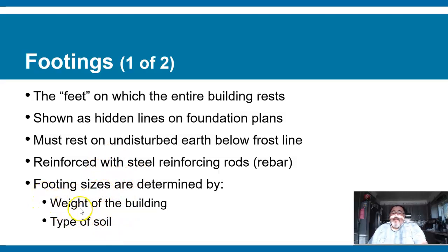So when you get plans, some engineering has been taken into consideration with the type of the soil and the weight of the building, and from that determined a footing size. So footings might be similar in shape and even size, but not always. You'll find that there are areas where they will get heavier or thicker to make them stronger, or they will add more steel reinforcing.